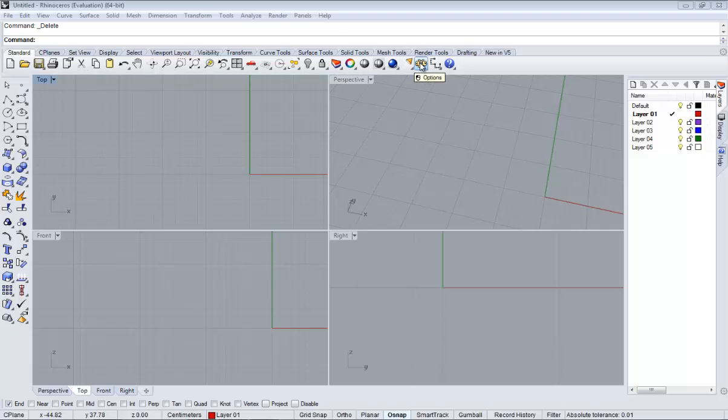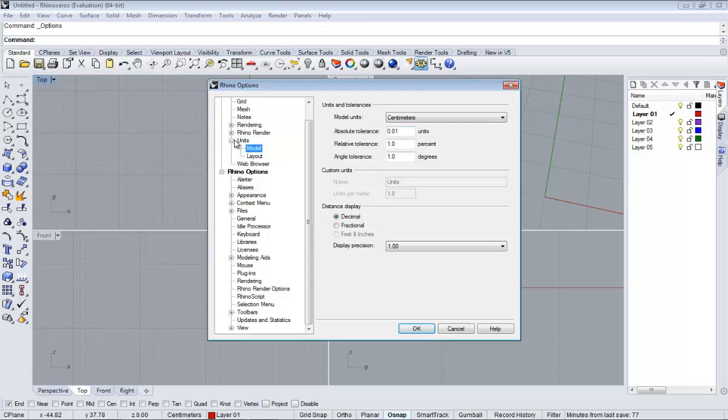We're going to open here on options, and if you check here on document, under document properties, units, model, just make sure that it's in centimeters. So far we haven't really worked with measurements, with dimensions. Now we should, because now we are going to make something real. Centimeters.